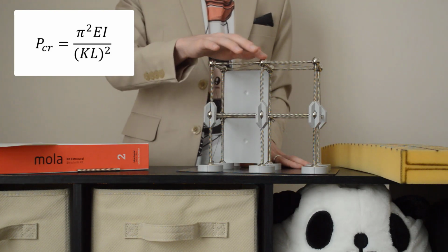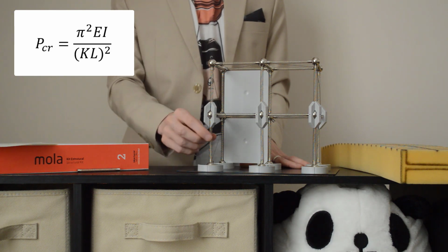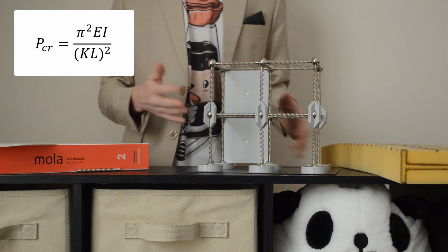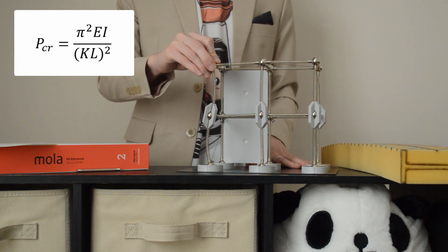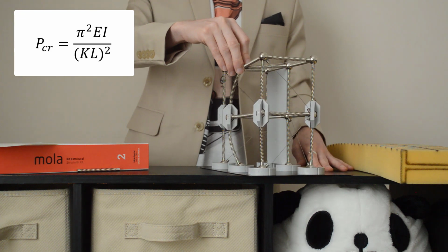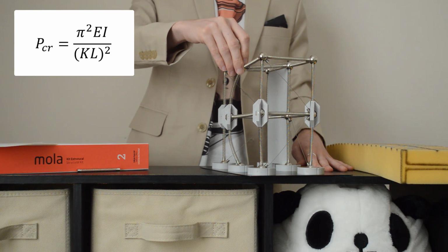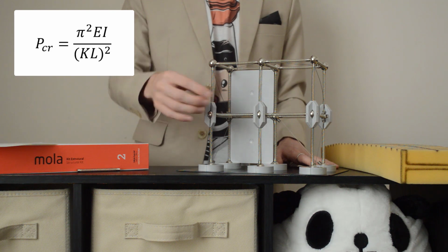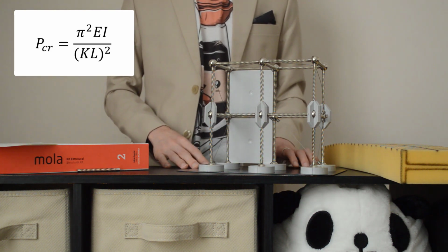Now let's jump to this column here. Note that it's the same overall length, it's the same material, this sort of springy metal. So theoretically, if this were the same type of analysis as in tension, we would see the same sort of shape occur. However, you can see we don't get that same S shape here. Instead, we get this C shape. So clearly there are some other factors at play here beyond just the material and its cross-sectional area.